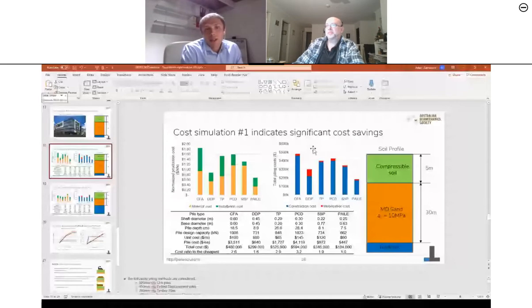If you consider how the pile is working in the ground, typically bending moments become negligible within 10 diameters of the pile from the surface. Because this pile is slender, it's only 250, it would be sufficient to introduce a 2.5 meter pipe. And it's easy to handle on site. It can be done by an offsider pretty much. So no need for cranes or expensive equipment.